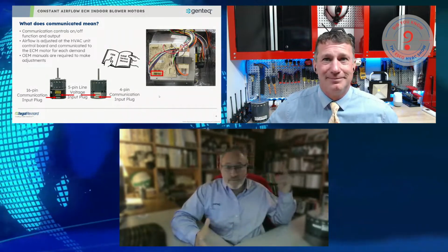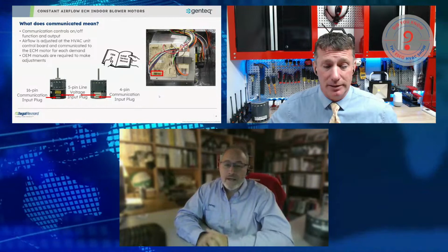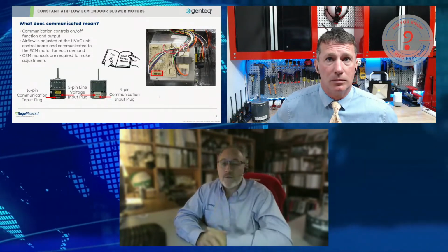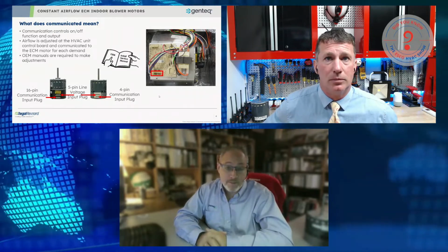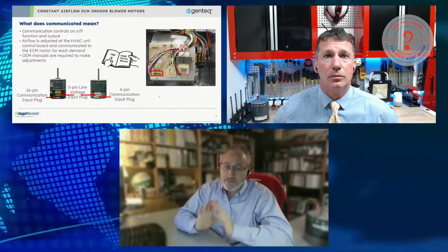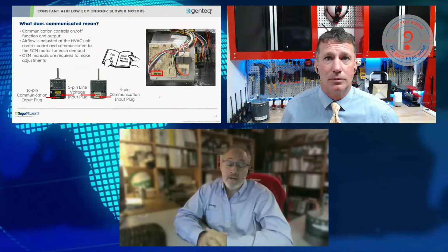Today, you're going to get them all on your phone. You're going to Google a model number and probably find it. But become that technician that on every job pulls up the manual, checks to see if the system has ever been set up properly, and measures the airflow. You will just be amazed at how much better systems will run, how many fewer repairs you have.